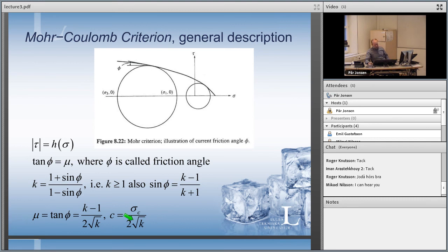And the difference will be, theta will be this one. As you can see, at lower pressure we have one friction angle, and at higher pressure we have another friction angle. Then you can put it as a function instead and have this nonlinear envelope here. If you know this one, you can have something called K, and K should always be 1 or larger than 1.